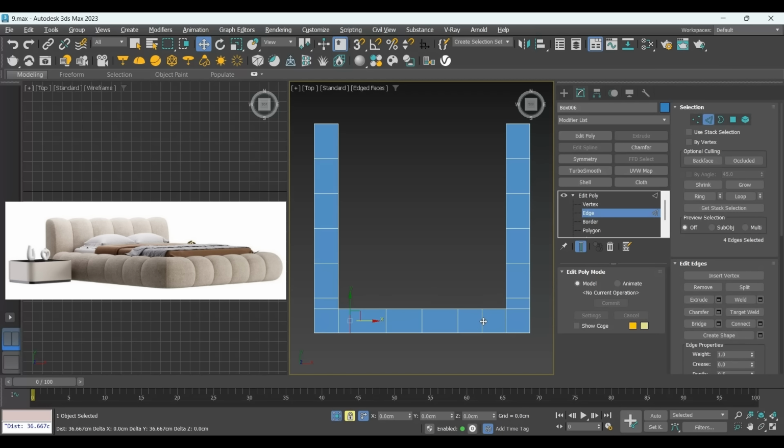And the same thing, I will do it for this loop. First, I will turn off the lock selection, double click, move it to the back, and now you lock the selection and move it with a reference point from here to here. Now these edges have the same distance between them, and the remaining area I will keep for the corner, because you can see in the picture that the corner has a different geometry. It is a separate one.